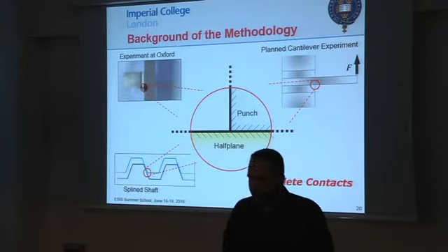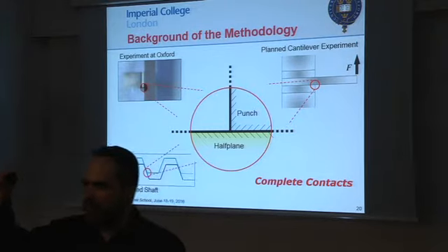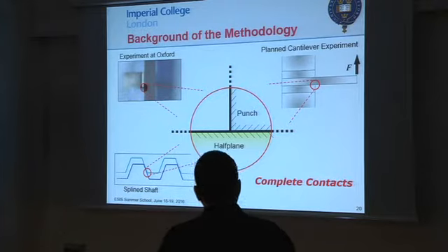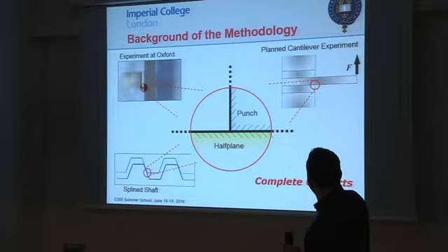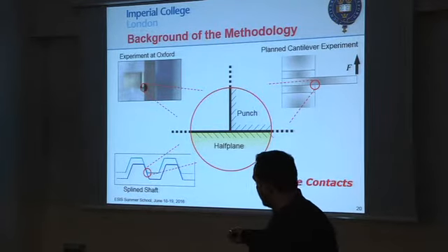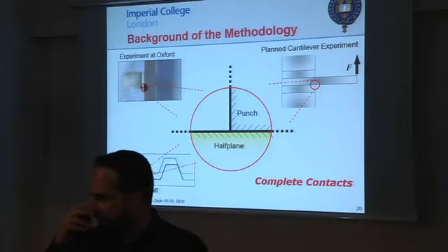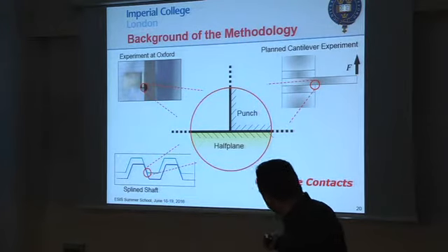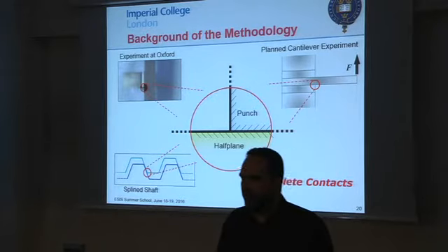You can think of lots of problems that have this kind of issue. So imagine you've got a cantilever beam and you clamp it with something which is fairly sharp. If you try and apply load to the cantilever beam, that corner has the same problems as that corner or that corner. So the idea is that you can represent a lot of things with the same solution of a simple problem that has a sharp corner, as long as you know how to do it.